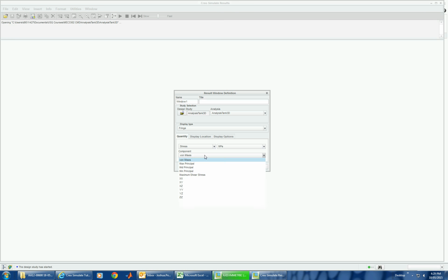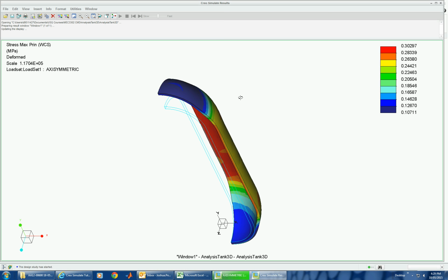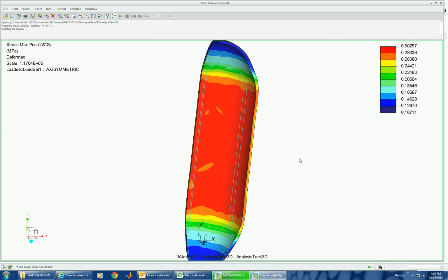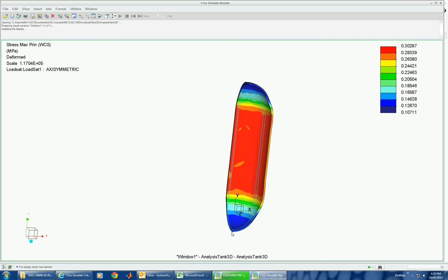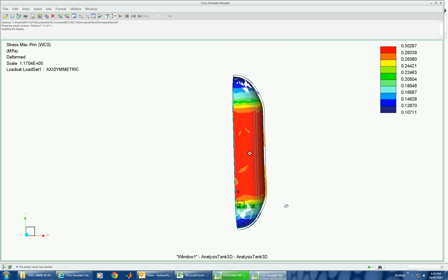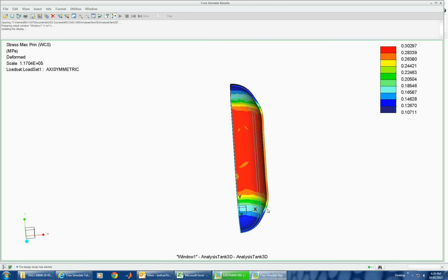Let's check out the result. Some deformation, and there we go. You can see that's moving freely in the Y. That point is constrained but not causing stress there. And you can see this is expanded out due to pressure. Alright, so that's what we would expect to happen. And here we've got very low stresses because the pressure was too low. But that'll do for now.